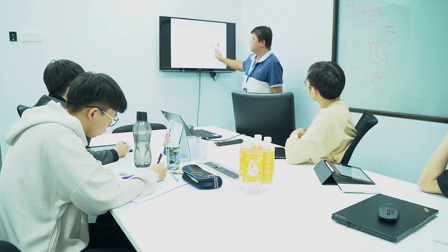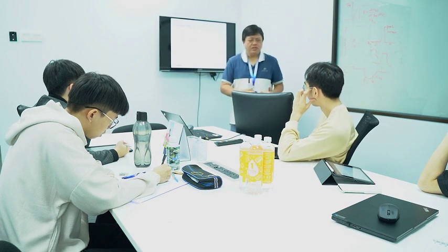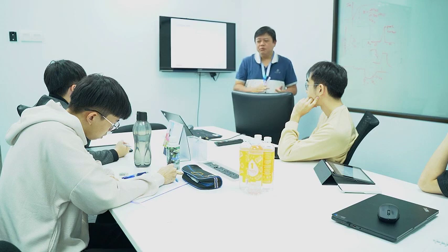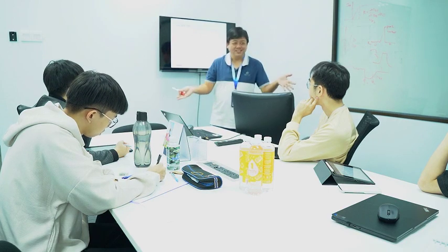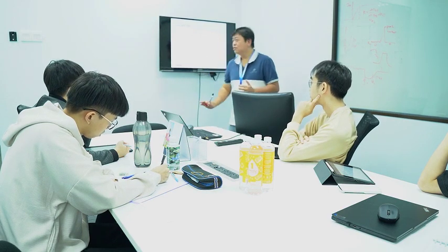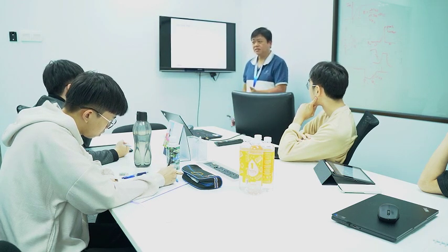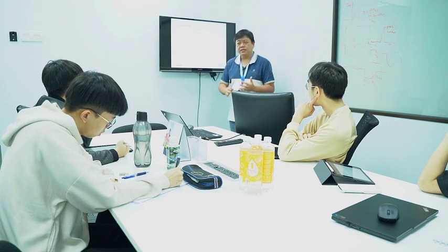So that's why it's very important to say, like some of you told me, one pole contributes a maximum of 90 degrees of phase shift. So in a negative feedback loop, we need to budget how many poles we can afford to have, so that the phase shift doesn't reach 360 degrees and cause oscillation. You need to budget that, right? And you also learned that at the cutoff frequency there's a 45 degree phase shift, and the maximum is 90 degrees, right? All this information we need as an analog designer to design a negative feedback system. Very, very important for us.